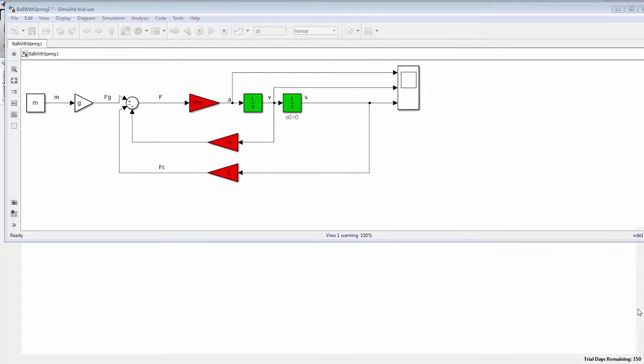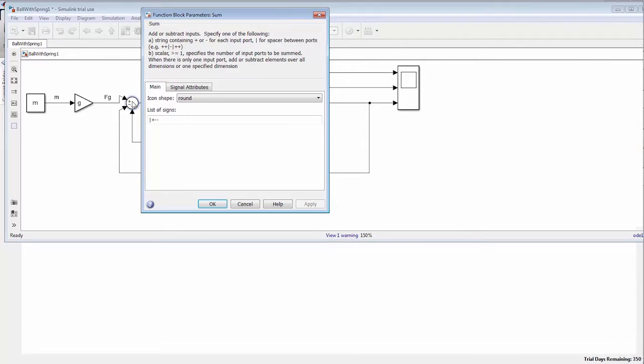And for the other point, the Simulink specific, I will change to Simulink once again. What I don't like personally in this model is this signal line here. Yes, it changes direction 2 times without any good reason. The routing is pretty nasty. And there in this sum block, you already saw it some time before, there's this vertical bar. And this vertical bar acts like an invisible input port. But that influences the distribution of the input ports around the circumference of the sum block.